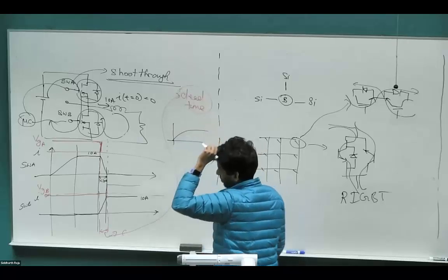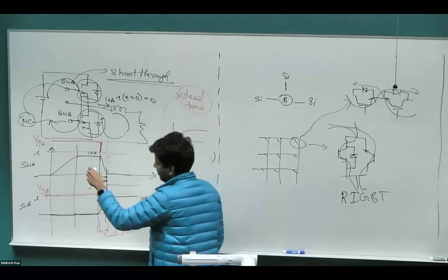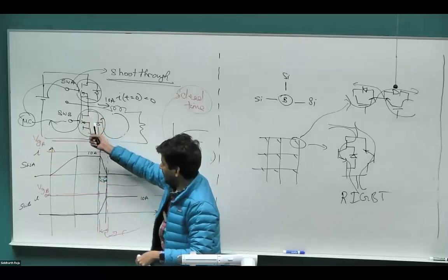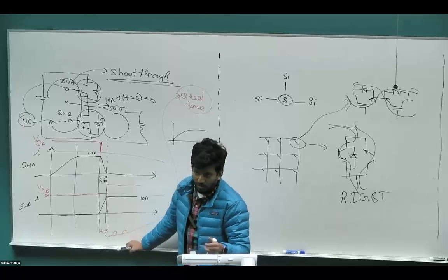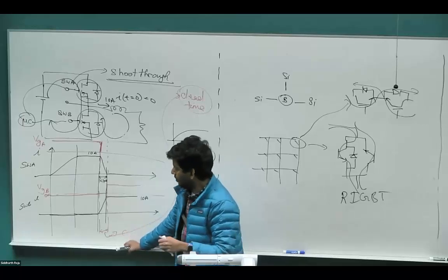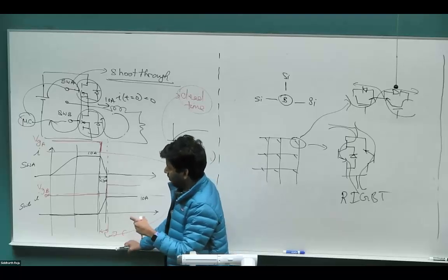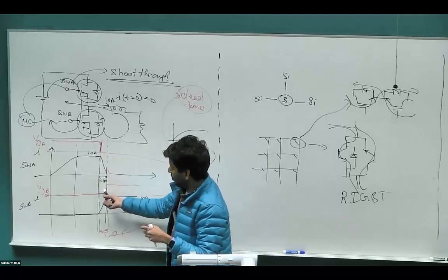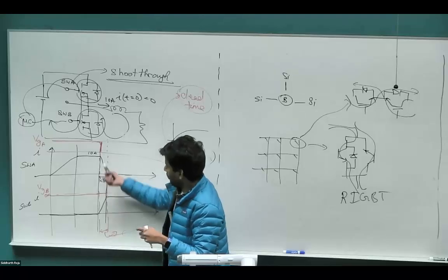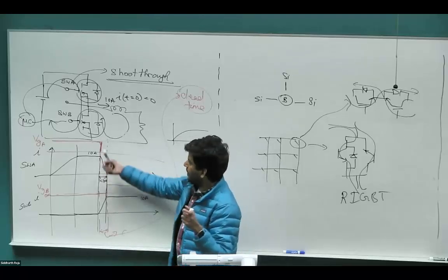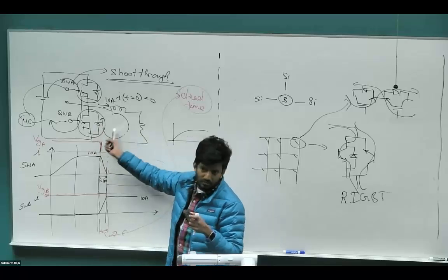So in your microcontrollers, you would typically have some PWM module where, depending on the switch that you have used, the data sheet will tell you how long it will take to clear out the charge and the turn off and turn on times. All of those are given depending on various operating conditions. And then you'll program it into the controller that before one switch turns off and the other switch turns on, there should be some amount of time where both switches are off. Right? When both switches are off, the diode is the pathway that it conducts through.